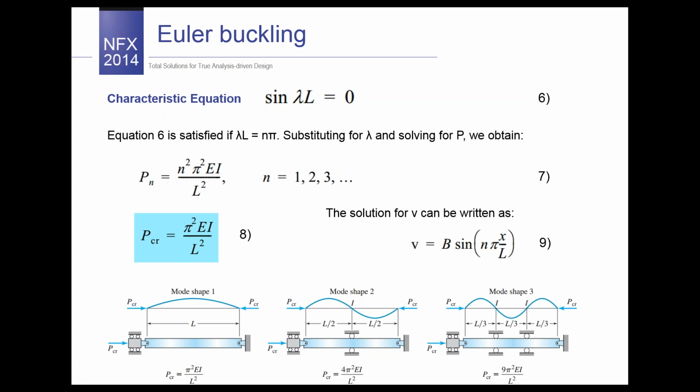The importance of each buckled mode shape can be appreciated by examining the figure below. If buckled mode 1, which I am showing you right now using the cursor, is prevented from occurring by installing a restraint or support, then the column would buckle at the next higher mode, at critical load values that are higher than those for the lower modes. Point Y, for example, on the deflection curves describing the mode shapes has two attributes.